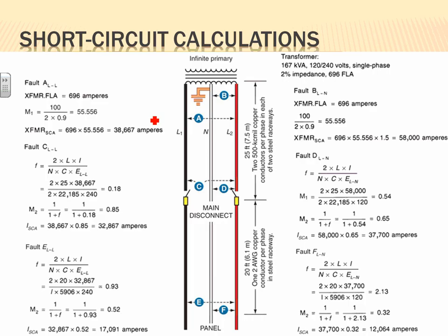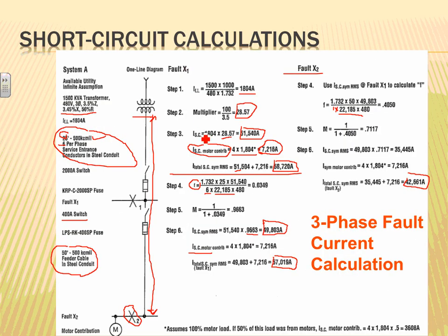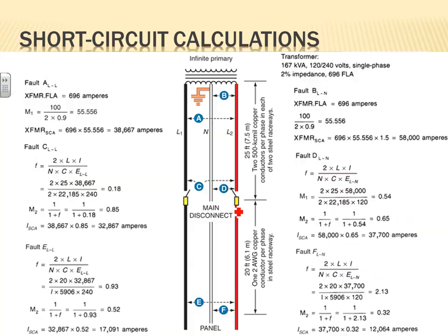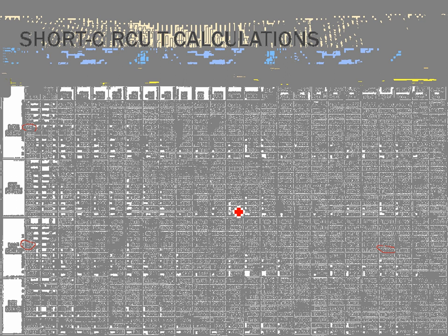So it gives you the impedance of the cable anyway. That will give you the impedance of the cable to do the calculation right in here. That number at the bottom here is the impedance of your cable, the contribution to the impedance. So if you don't have the software, that's what you're supposed to go get that sheet. All these sheets are available right here in this book, that's available free. If you want to look at it online, there's a PDF file of it.